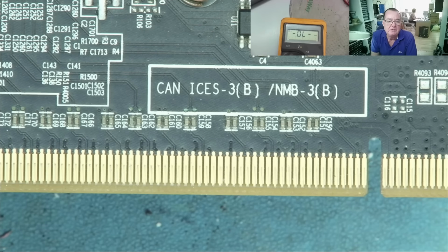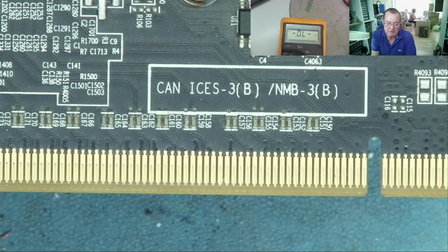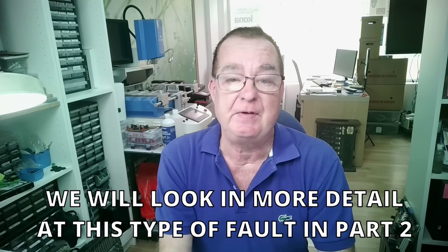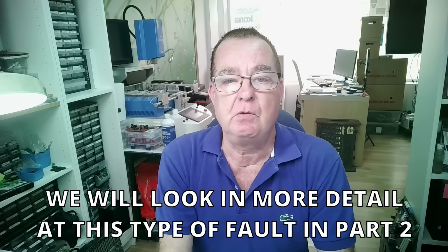Okay, so we can say that all three cards read okay, and I think you've now got a good idea of what to expect to find and what to look for. And we'll leave that one there, guys. So at the moment we haven't even taken the heatsink off, but we've certainly tested some things. If you have a problem where you found a short on the 12 volts or the 3.3 volt rail, that's something we can probably fix, or hopefully we can fix. It depends on what damage this caused.